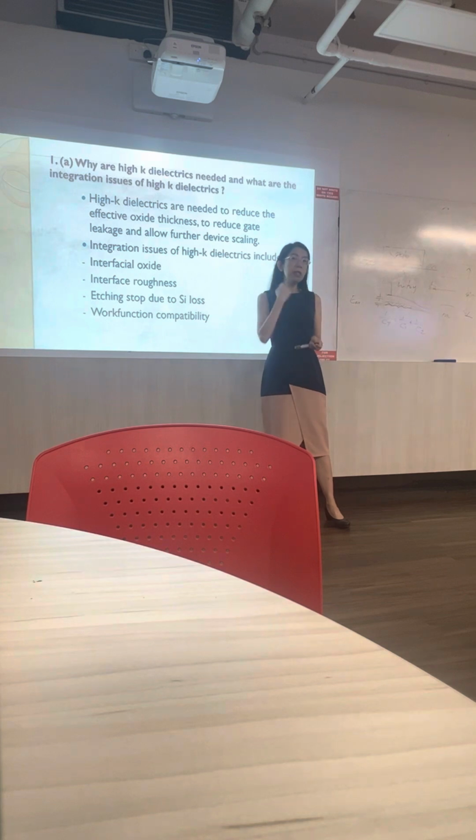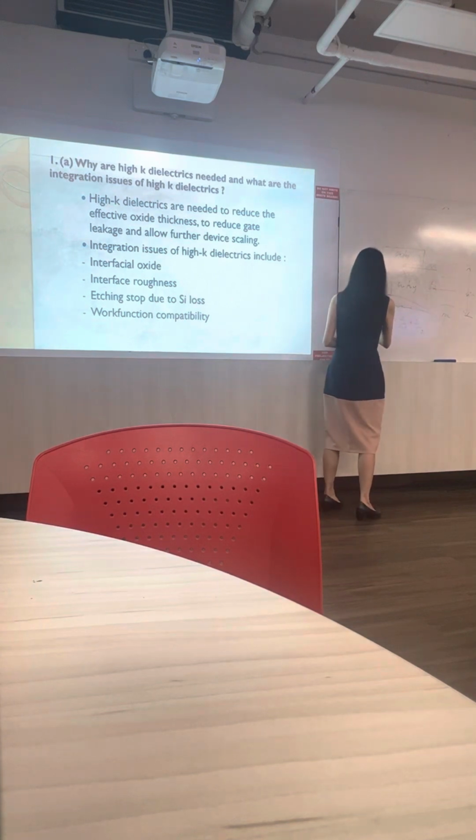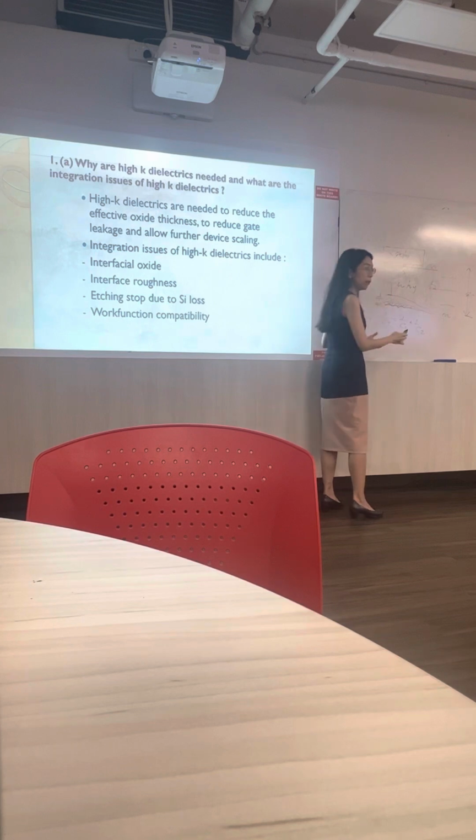Right, thermal stability is another key concern. Yeah, that's correct, because very often we find that when you increase the temperature, any metal oxide, let's say hafnium SiO2, has a tendency to take in some silicon. It becomes like hafnium SiON